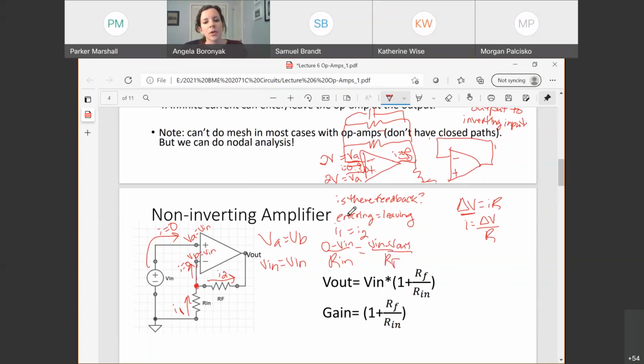Okay. I now have an equation that relates VN, the voltage that I'm applying kind of into this op-amp, in this case through my non-inverting input, and V out, the voltage I will get measured at the output of this op-amp. Let's rearrange it because I would like to solve for V out in terms of VN. As a hint, we should get this as a final answer. Let's prove that to ourselves. Again, we did this based on nodal analysis, looking at current at that node. So how am I going to solve this for V out? I want to get V out by himself.